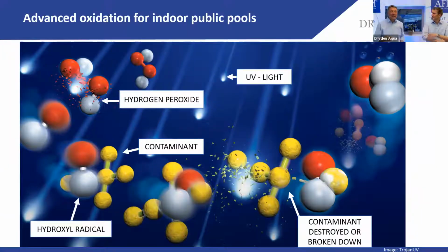You see these photons jumping in and cracking the hydrogen peroxide into hydroxyl radicals. And then they go to the contaminant and they oxidize all the bonds. No disinfection byproducts. And this is why you use them very often in wastewater, especially industrial wastewater, where you have heavy toxics like benzidine, etc. If you want to remove them, the cheapest way to do this is hydroxyl radicals. And by the way, this is where we learned it. We have seen this in one of our applications in water treatment.